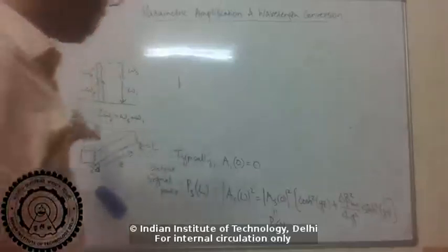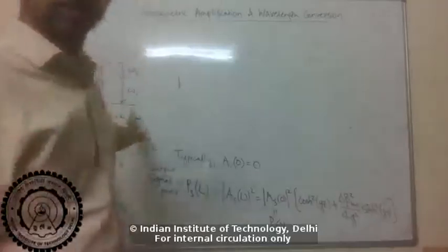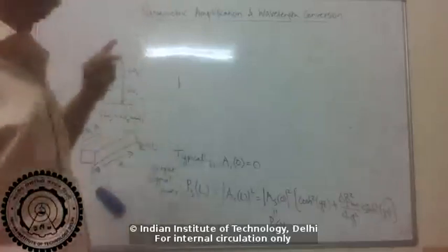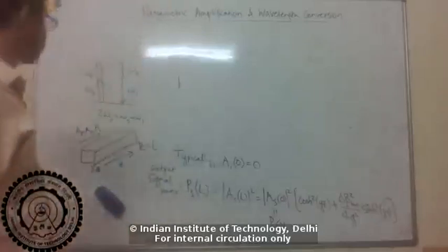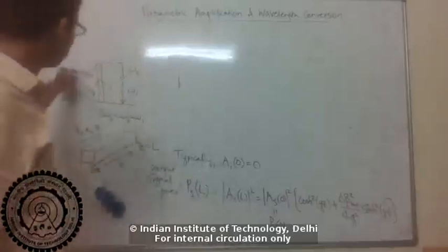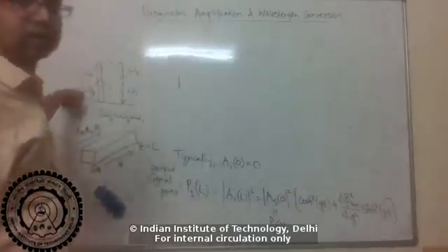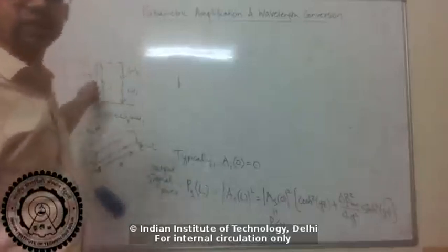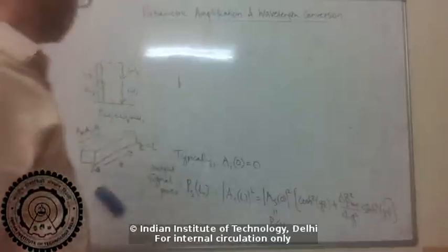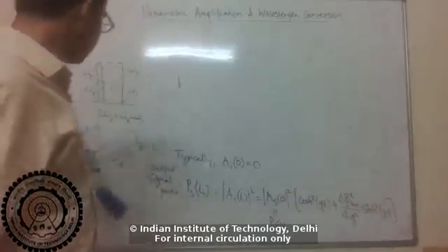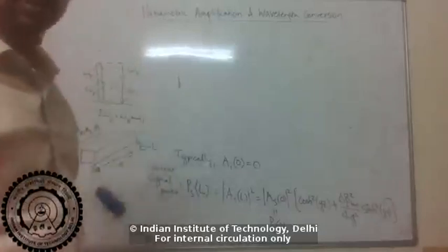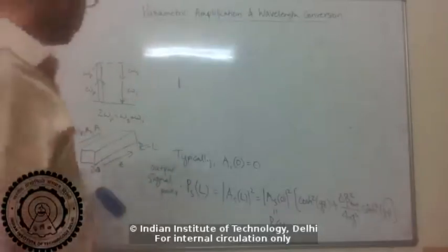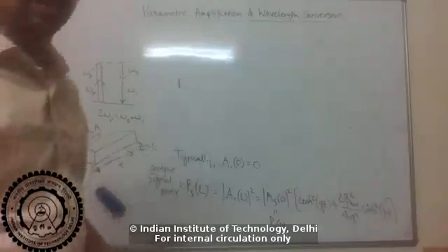So in actuality, physically, you are only sending three fields, and only three fields are interacting in the waveguide, although it's called four-wave mixing. In the general case, you can send in two different pumps with two different frequencies, and you can again have them co-propagating, for example. You can set it up how you want. So we can also consider the case that you are suggesting.